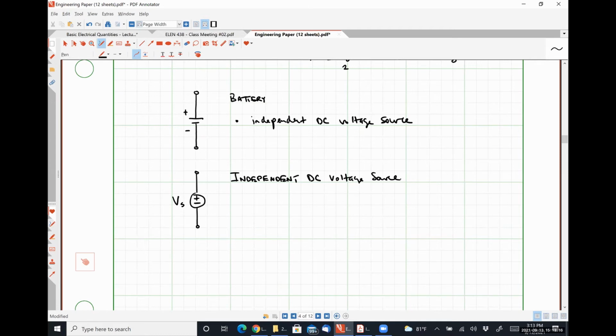So like a fully charged AA battery probably has somewhere between 1.55 and 1.6 volts across its terminal. And a fully discharged AA battery is just going to be somewhere around 1.4. And so all that really means is it isn't able to sustain current anymore, okay?